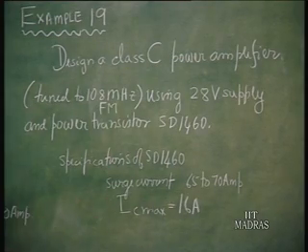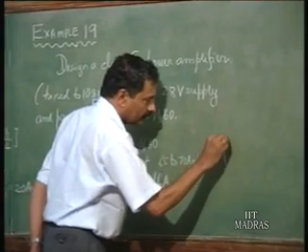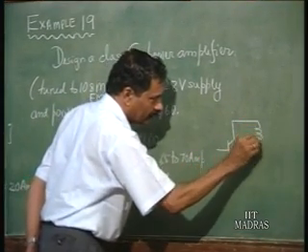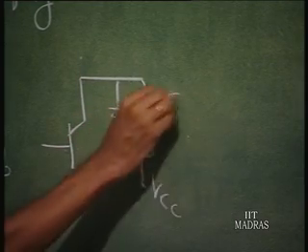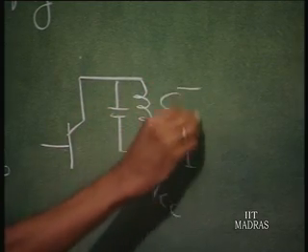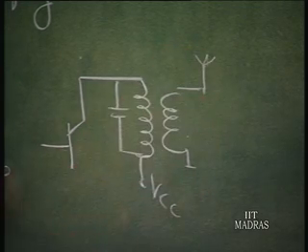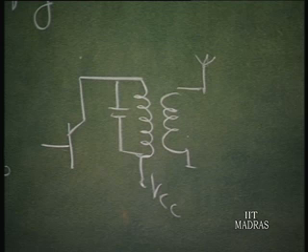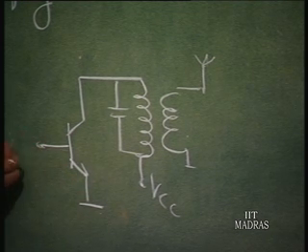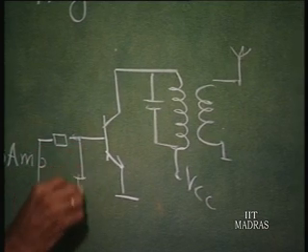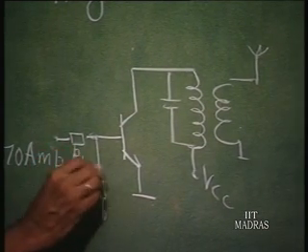Let us see. We just said this shall be a transistor with a tuned circuit, this might really go to the antenna, like that. So, we have here now an arrangement, let us say, to bias it so that it will work with a certain amount of conduction angle.